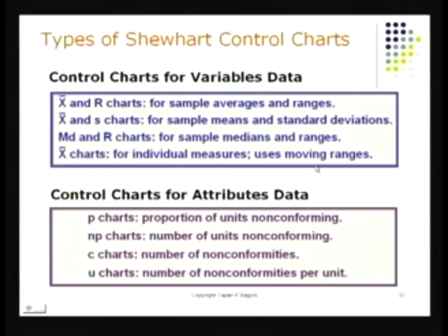Now that you have understood what control charts are, you've looked at an XBAR chart and an R chart. I'm going to be showing you some more of those. The other charts are all very similar. The spirit is the same. Try to distinguish between exceptional variation and natural variation. The moment there is exceptional variation, this is when you'd like to take some action, and leave the process alone if the variations are natural.